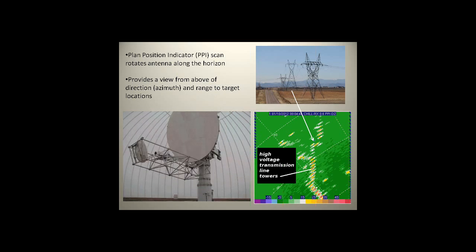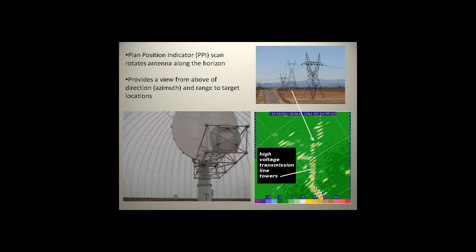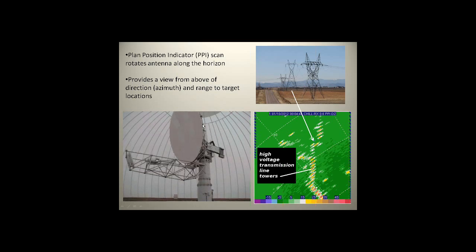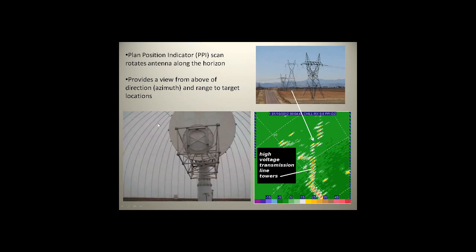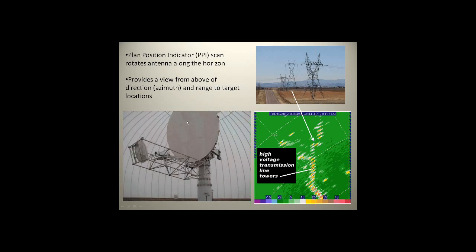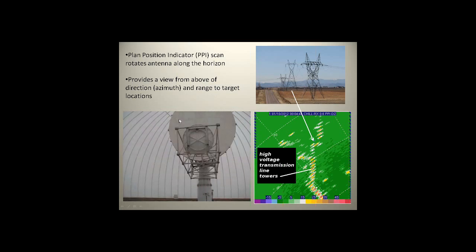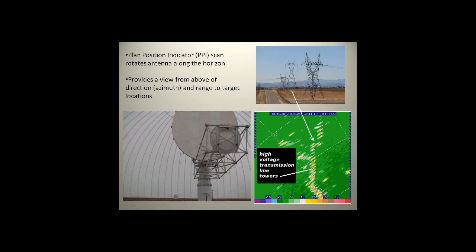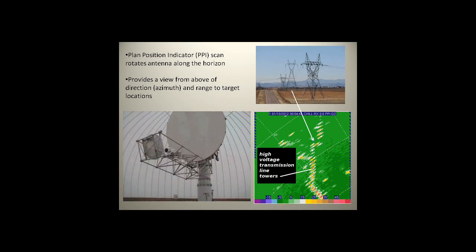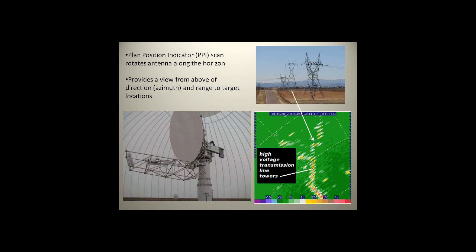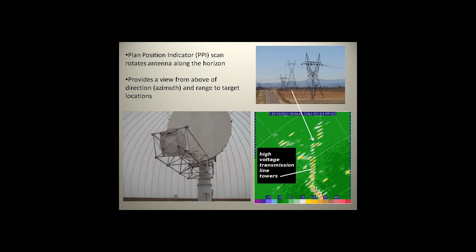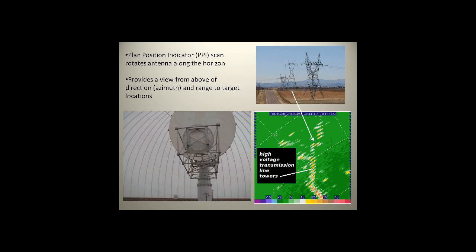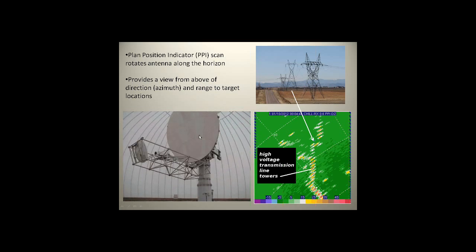So there is active research underway to do electronic scanning, using a different kind of antenna. Instead of focusing your energy with these metal surfaces, imagine a flat-face antenna with many, many little emitters distributed on it, little dipoles. If you phase those emitters properly, so your signal arrives at one part of the antenna at a different point in time than another part, the individual radiation from those dipoles will constructively add, and you can steer the beam around in space electronically, which you can do much faster than these mechanically rotating antennas.